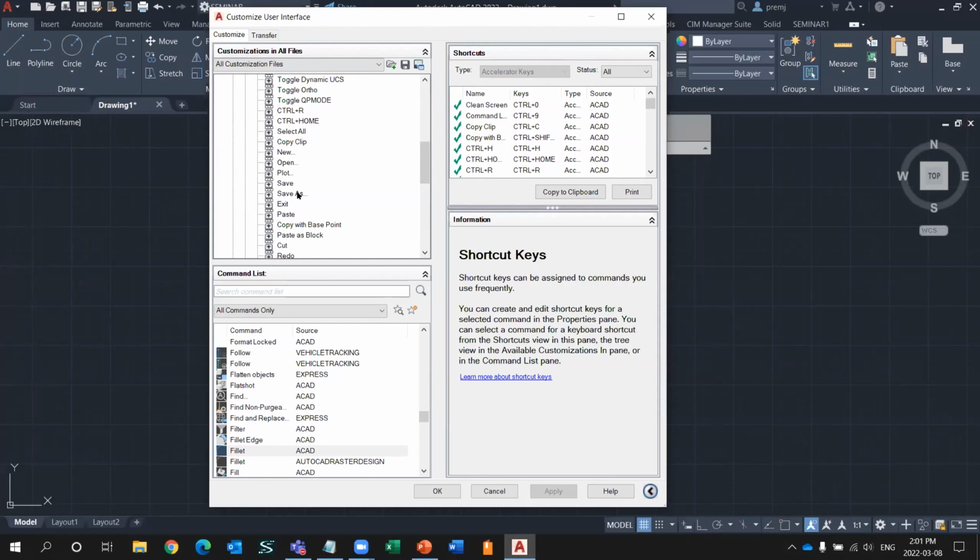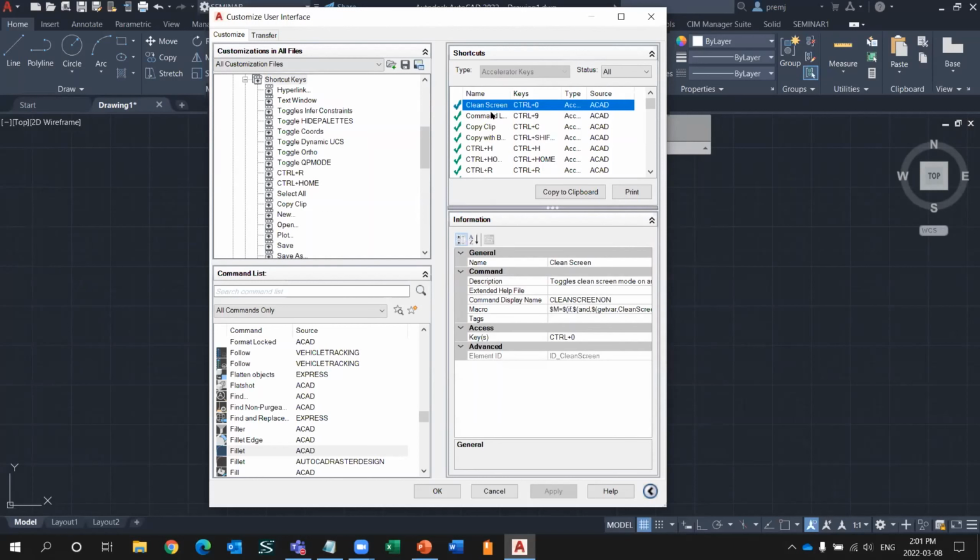But in addition to that, you could have the AutoCAD commands launching with the control keys. One example is Control+3, tool palettes coming in. You can see the complete list over here. Control+9, Control+6 is DB Connect. So these are the out-of-the-box ones.